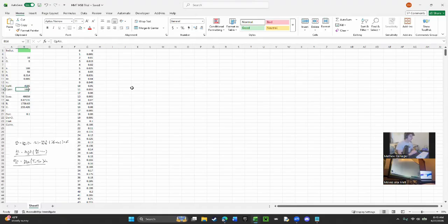And then I just Googled these in advance. These are the heat capacities of water and air. We have the enthalpy of vaporization for our system, which I also looked up. And then these are the Antoine's coefficients, which we're going to be using to find the saturated pressures of our system. I'll get into that in a little bit. And then we have the density of the air going out. And then we have the concentrations for air when it's fully saturated and when it's initially going in.